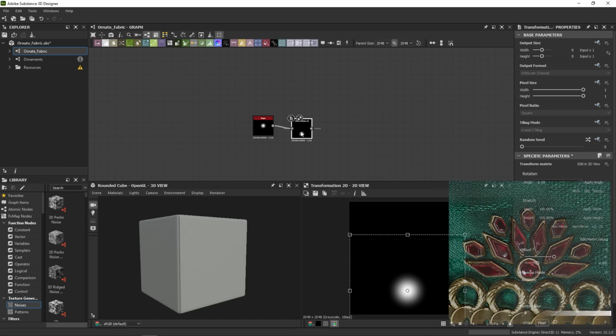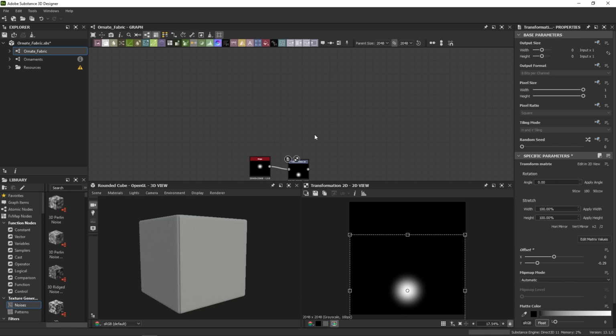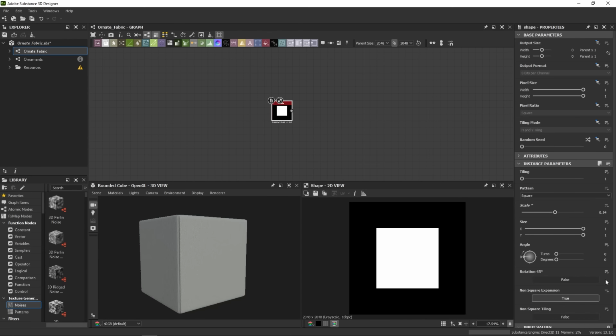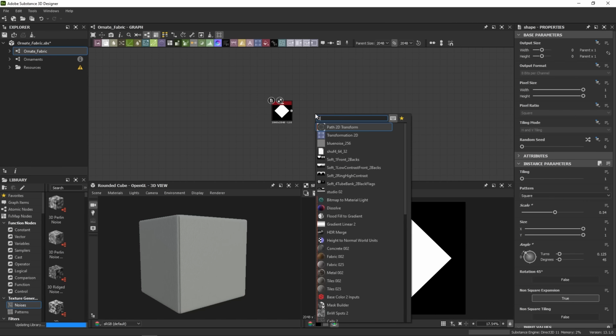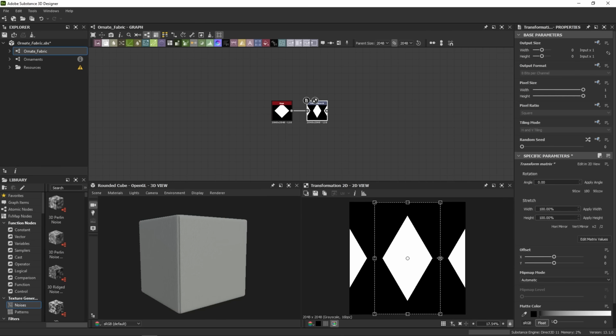All right. Then we have these diamond shapes. It would be interesting to see how you would approach it based on the knowledge you gathered in the previous videos. What I like personally about this shape is that there are different ways to make it, and they are all perfectly valid. I'm going to show you a few of them. The first that comes to mind for me is taking a solid square, rotating it 45 degrees, then squeezing it with the transform. Again, when I do that, the shape is repeating on both sides, and I don't want that, so do you remember how we can fix this?